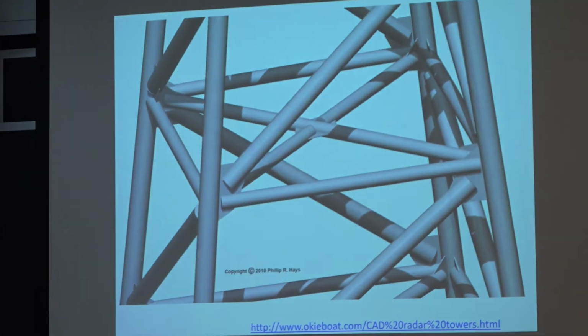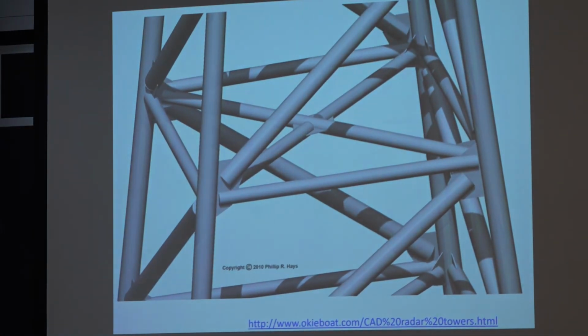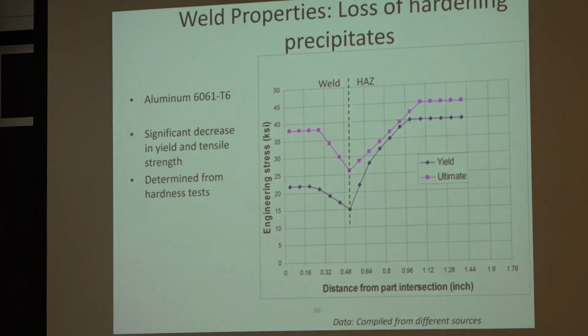So that's an example here of a crane that has the gusset plates and is essentially more able to resist cyclic loads without a failure. There was a crane collapse that we went over, and that was one of the problems. You know, they had these things welded to the corner and get transverse weld.